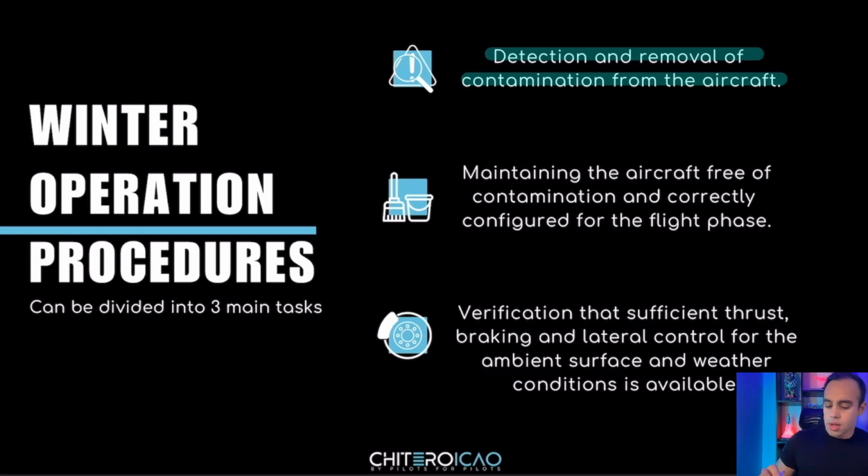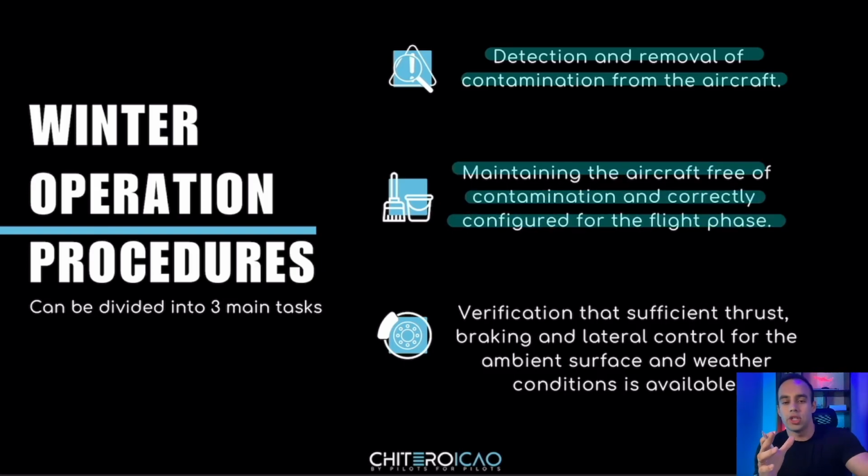After removing it, I cannot, for example, clean the airplane and wash it with water. That would be absolutely stupid because it's going to freeze again. We are talking about winter here. After removing the ice and snow, we are going to maintain the aircraft free of contamination and configured for the flight phase.